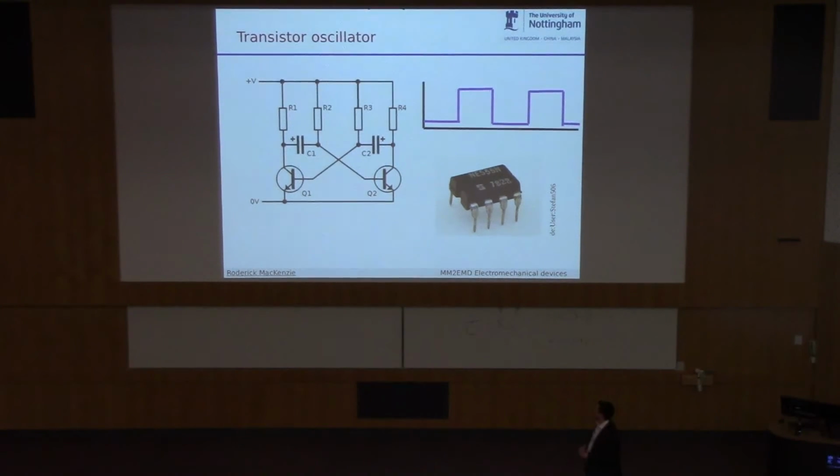And I just want you to know, basically, that if you make a circuit with 4 resistors and 2 capacitors, you can make a signal that goes on, off, on, off, on, off. And it's incredibly useful. And again, by tuning the value of the resistors and the capacitors, just like we did with the previous circuit, we can change the time period of that pulse. Now, I'm not suggesting you go and do that or buy that, but if you do want to make pulses like that, you can buy chips called the 555 timer chip, which is a very, very famous chip. And there are much better chips than that that will make these signals for you. So I just want you to be aware of this class of circuit.